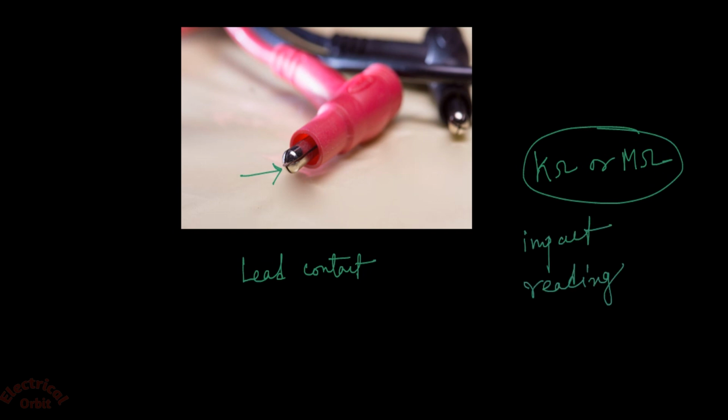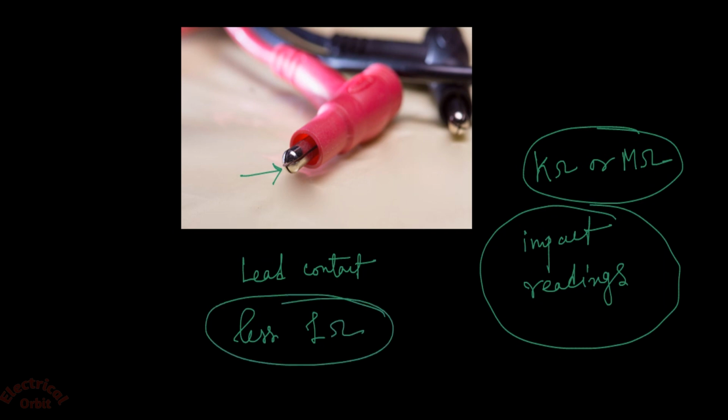But when the resistance value is less than 1 ohm, then the small internal resistance of the lead contacts has a great impact on the reading.